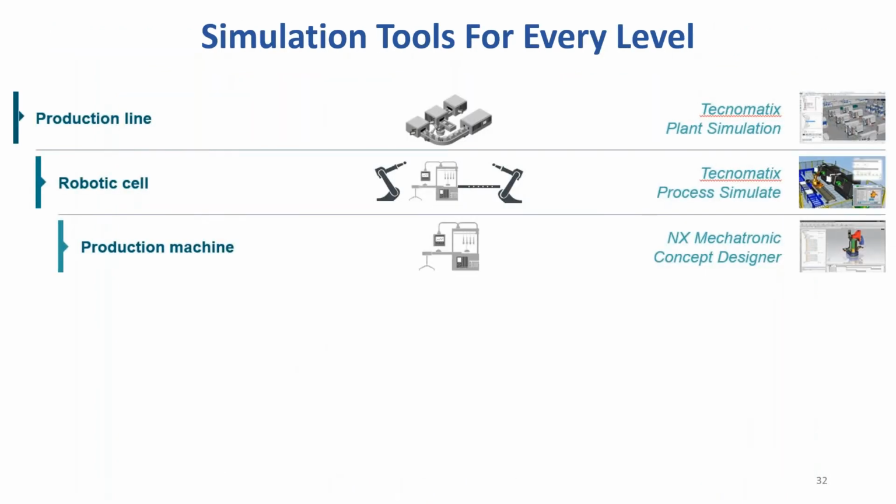Okay, I can't keep myself from gushing about these tools. I really think these tools are really cool. Another one is NX Mechatronics Concept Designer, which models production machines, and is another really cool tool. A functional model provides a common language for mechanical, electrical, and automation disciplines to work together in parallel. MCD allows you to not only see what it looks like, but validate how it works before you build it.